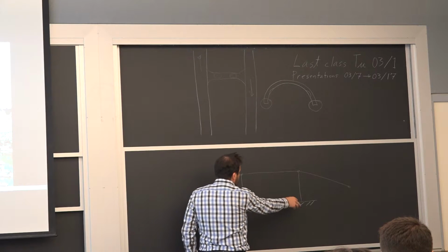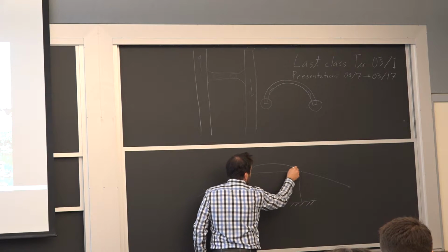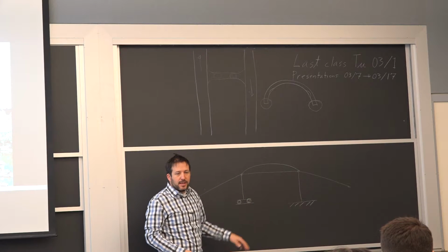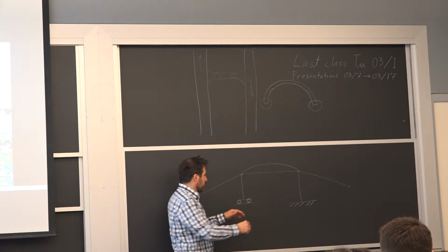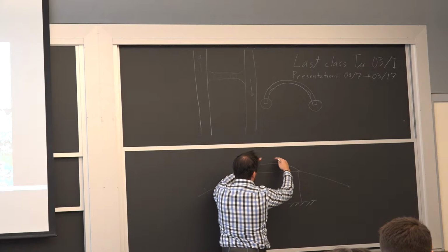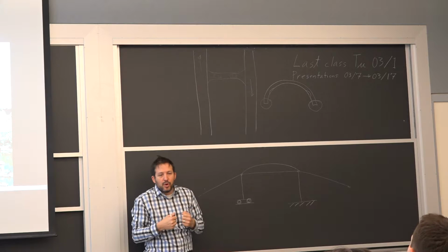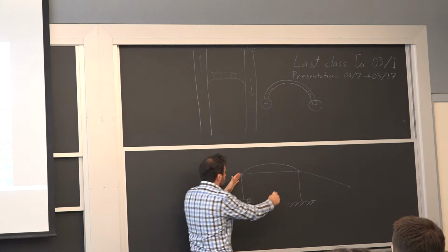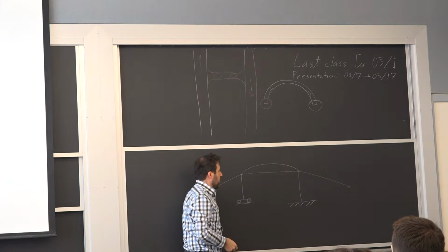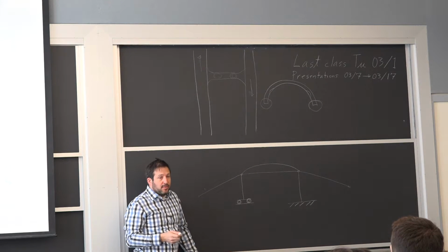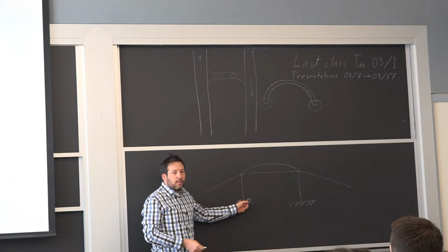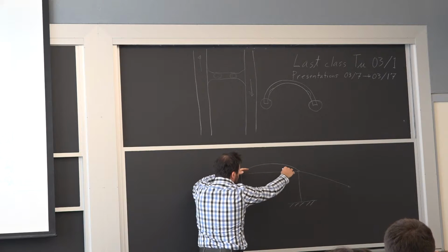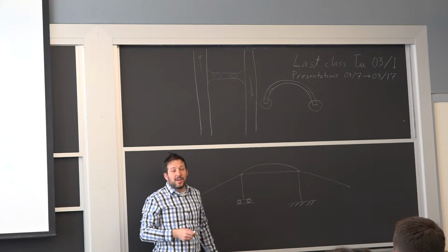Now, I don't have the distance exactly right here. This is really, really wide, and it has this arch structure. So if this gets fixed on a cold day, what happens after that is it's going to bow and build up a lot of compression when you heat it up. So as you go through the summer and you really, really are compressed, one thing that I believe happened is eventually you overcame the rust on this bearing. Now it starts to let go and releases dynamically.